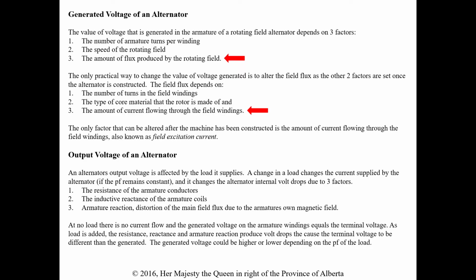So we definitely have to have a way to regulate our voltage to maintain that phase voltage or line voltage, or what they would call in this aspect terminal voltage. That's where you'd hook your load up to. It has to be a certain rating because that's what our equipment is rated to be hooked up at.